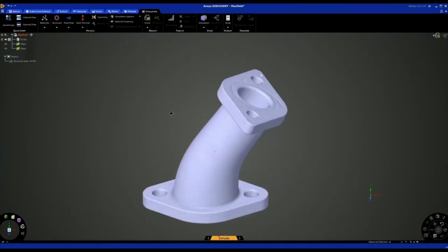To do this, I'm going to set up some faceted regions. I'm doing this by selecting regions that I wish to be used in the simulation. The regions that I'm first going to set up are the areas that may be supported. So we can see here, right click and add as a faceted region. This just means, one, it's going to be much easier to select, and two, that they can be used to actually add structural physics to them.